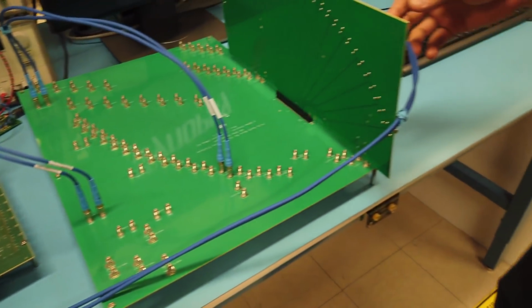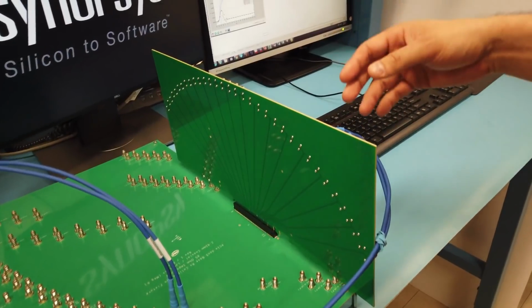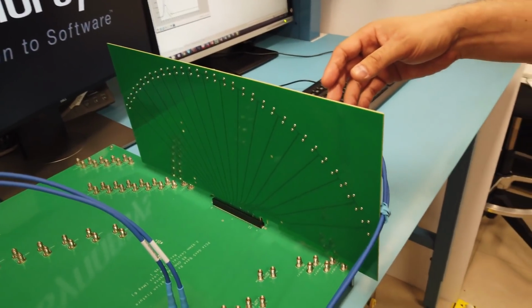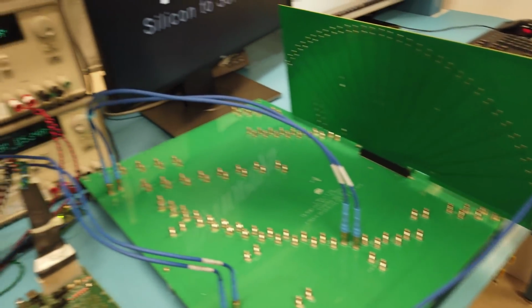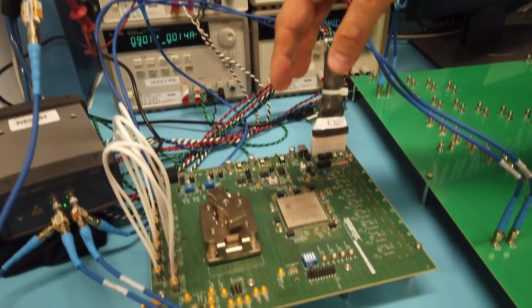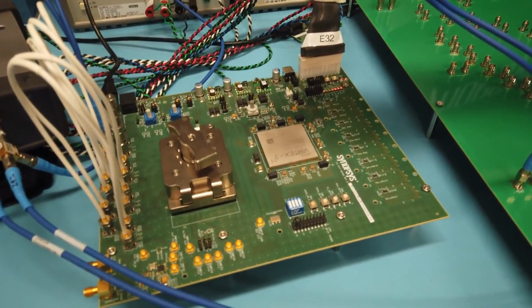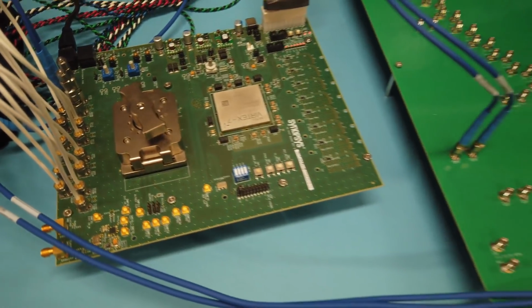This is the PCI Express Gen 5 base RX calibration fixture to make up the 36 dB of loss that's required per the spec. As we come out of that, we go into the Synopsys test fixture and into the receiver of our PHY IP. All right, let's go look and see how we perform under the stress condition.